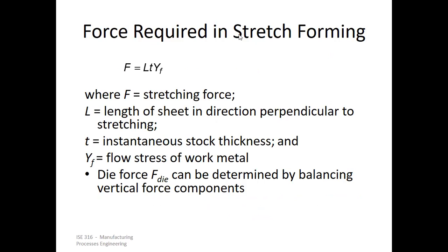Now, what are the forces required in stretch forming, right? Because we are also looking at the different force requirements in those sheet metal processes. That is given by F = L × T × YF. Very important to note what all these things are. F is a stretching force, as we know, that's what we are looking for. L is the length of the sheet in the direction perpendicular to stretching, right?